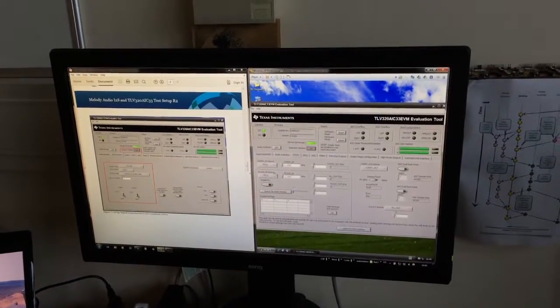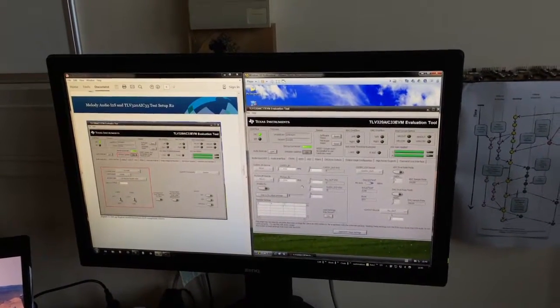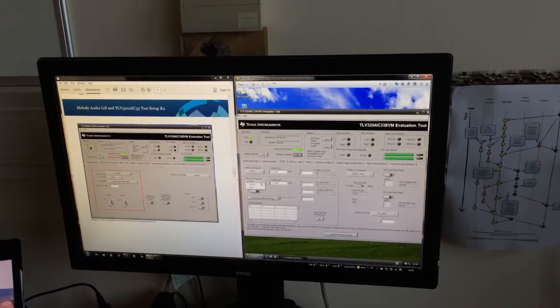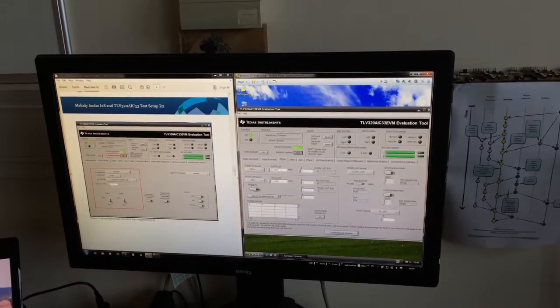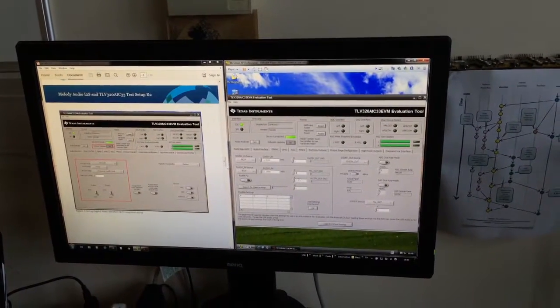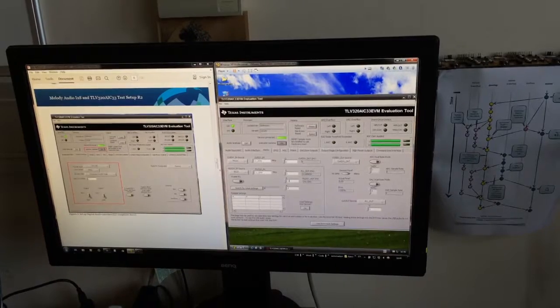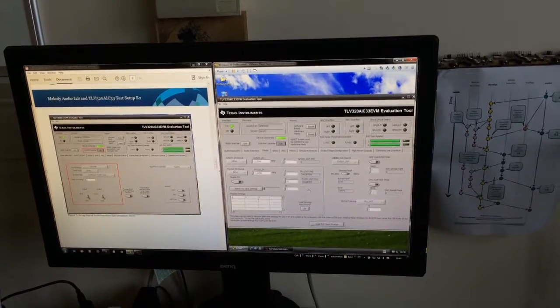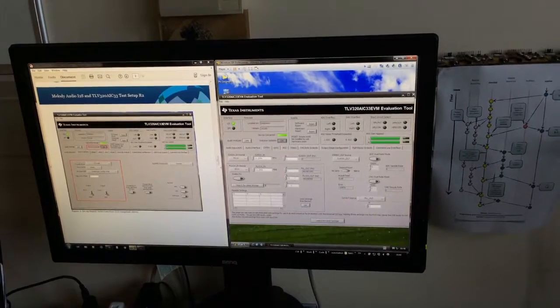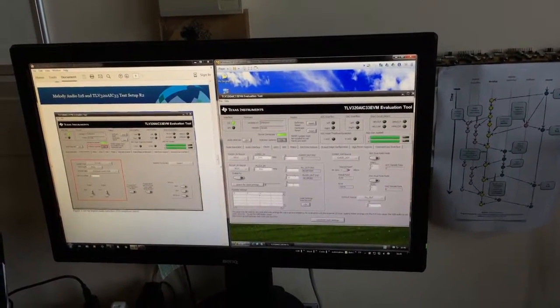The next pane selects how to clock the TI codec, and we are going to clock it from the bit clock of the I2S interface and supply it with certain parameters as specified in the application note. Basically, the P parameter is 1, the K parameter is 32, and the R parameter is 1.